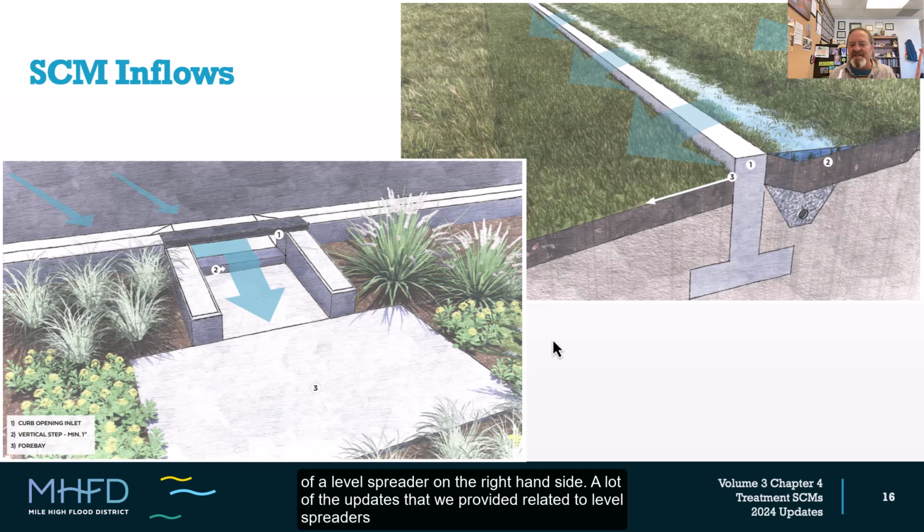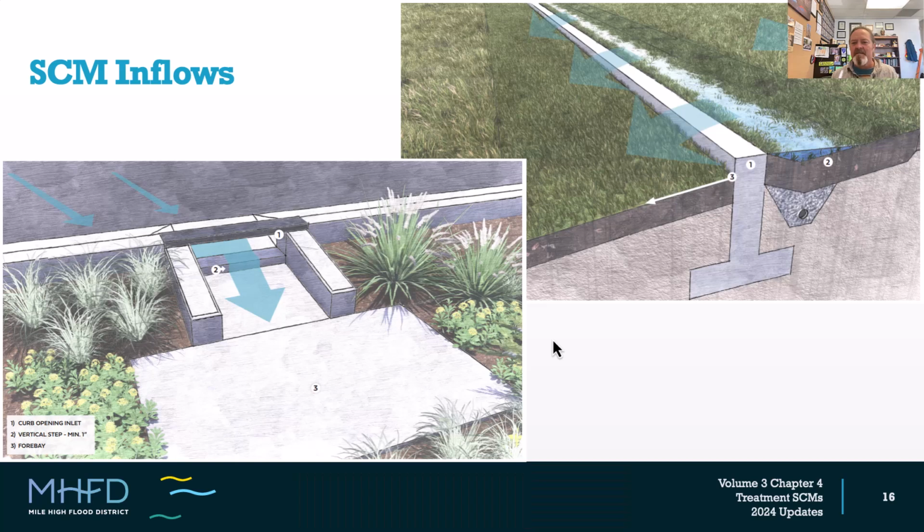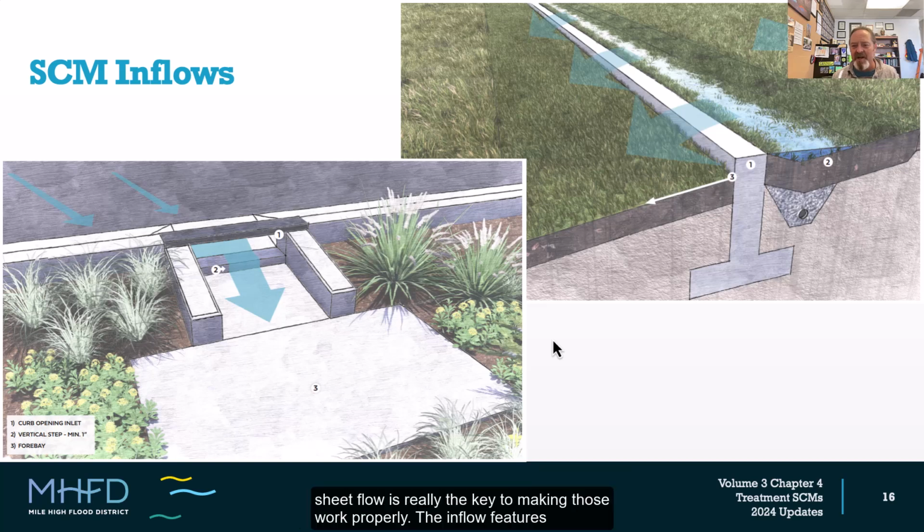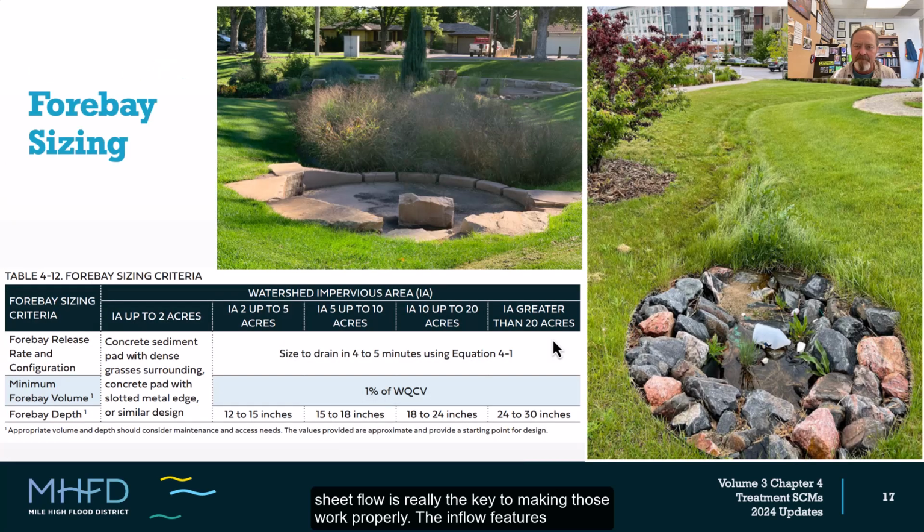A lot of the updates that we provided related to level spreaders were taken from research by Dr. Bill Hunt of NC State University, who's been studying the design and performance of level spreaders for more than a decade. And the sheet flow inflow features are particularly important because we've really placed an emphasis in this updated Chapter 4 on receiving pervious areas and runoff reduction, and sheet flow is really the key to making those work properly.